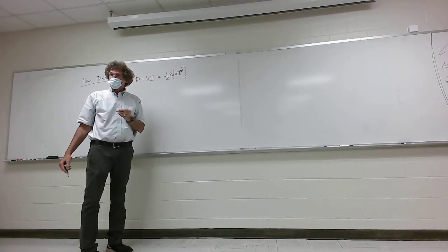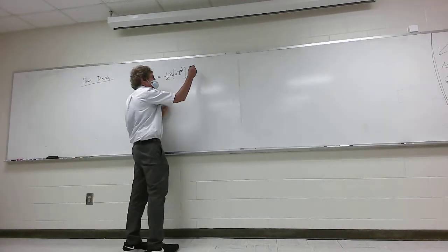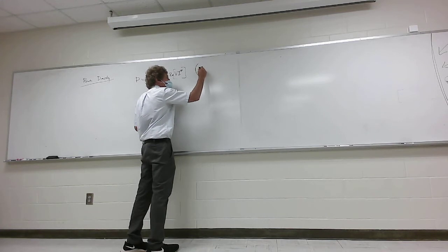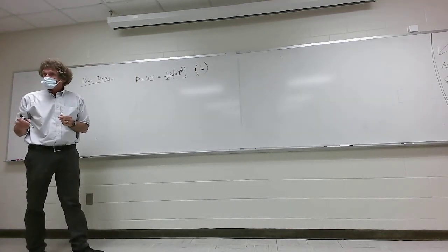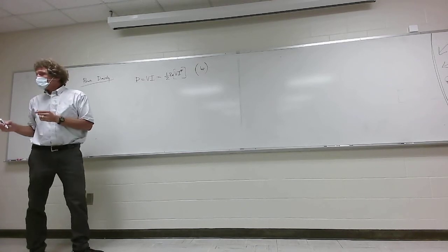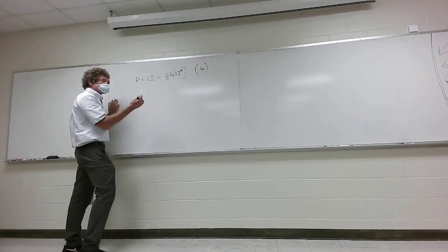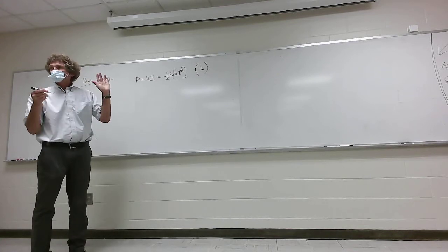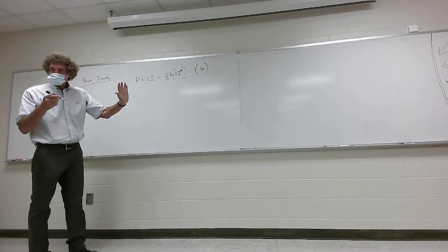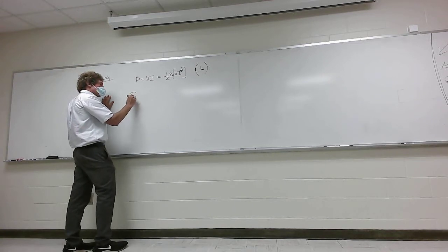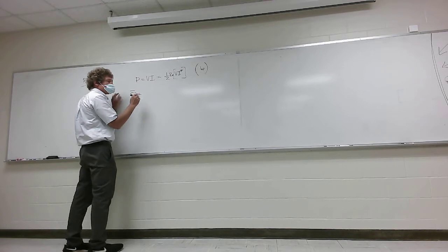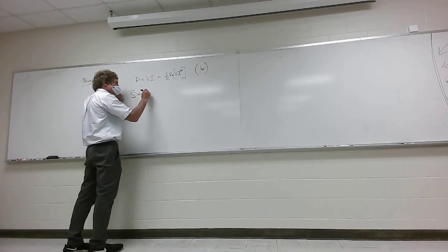Y'all got it? So I'm just trying to show you your prior exposure to power. What are the units of power, by the way? Real power. Watts, right? Real power is in watts. Now, when you're talking about electromagnetic fields that are propagating plane waves, then power in the signal is usually given by something called S, and S is equal to E cross H conjugated.